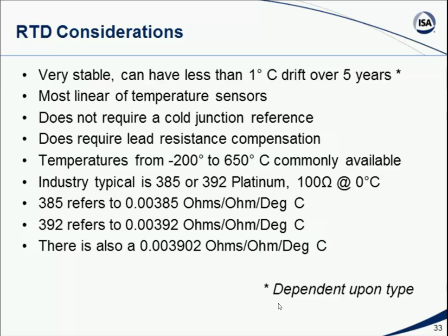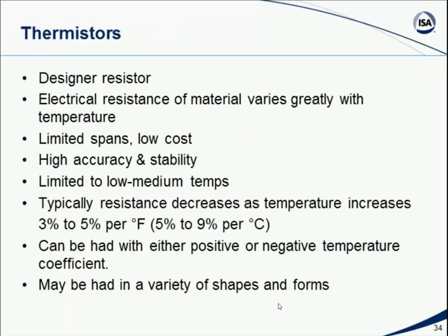So, again, devices change their electrical resistance based on their temperature. Now, another device that also has a resistive component that varies based on temperature is something called a thermistor. This is a relatively new device. It is a semiconductor device. It's not based on wire. It's based on the same sort of materials, doped silicon and such, that are used inside transistors.